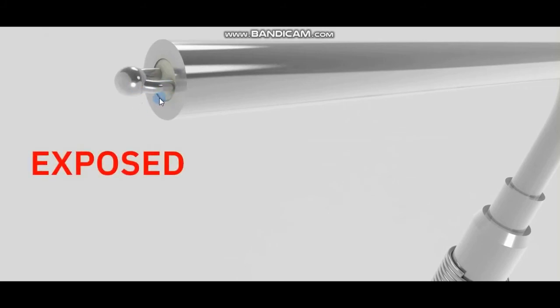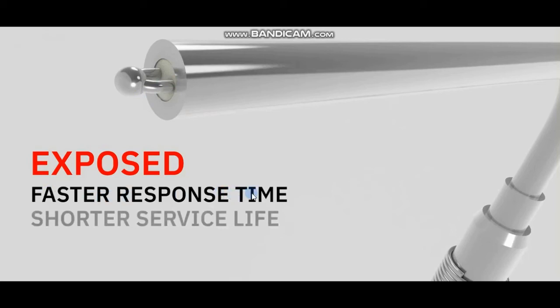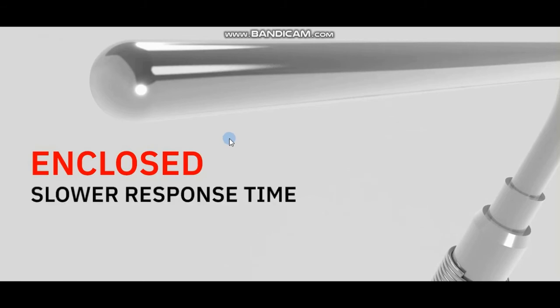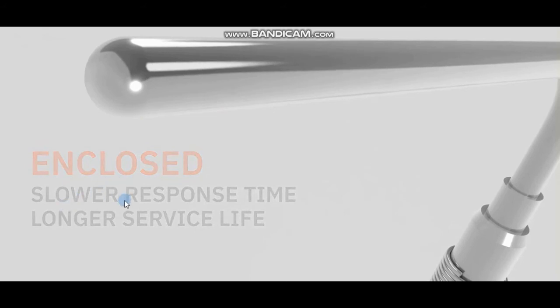As we see here, if the tip is exposed, it will have a faster response time, but it has a shorter service life. But when it is enclosed, of course, the response will be slower, but the service life will be longer.